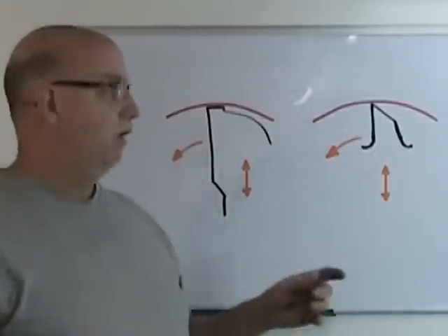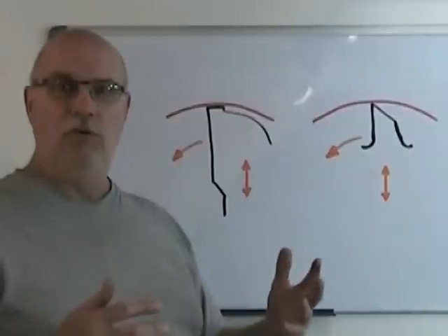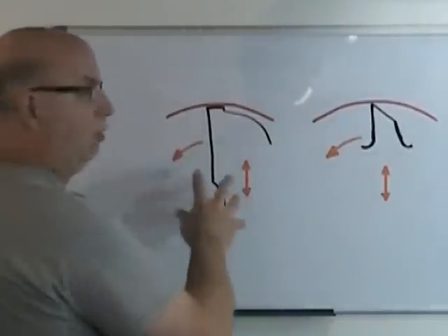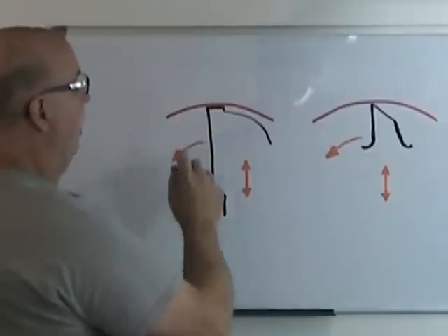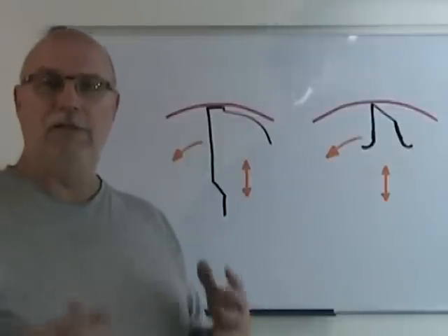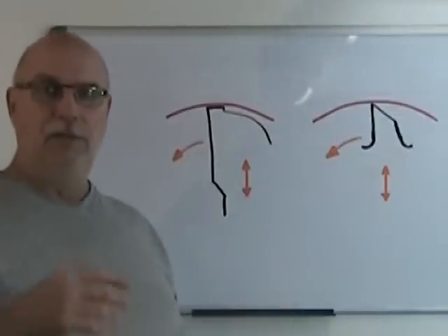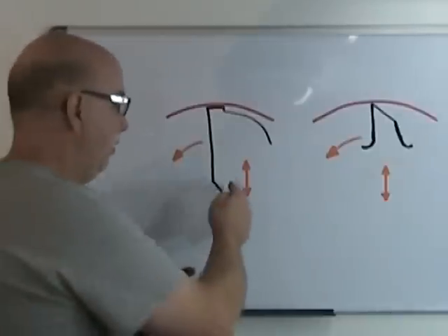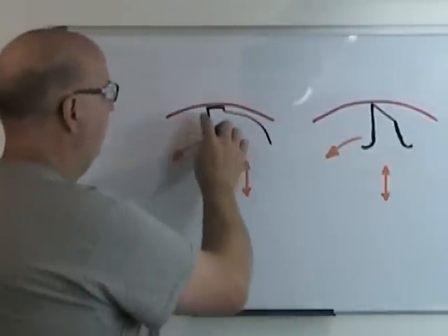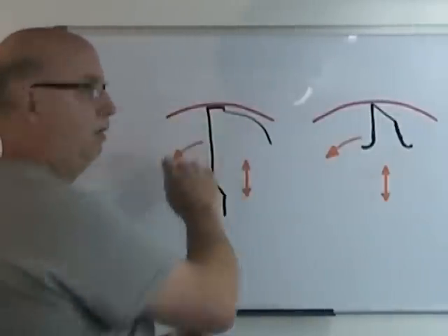It's not made to produce completely a hole, and there is no chisel edge or center cutting action on a reamer, because you can't have those equal on both sides and still get something that's accurate, because this tool, the drill bit, is center cutting. If it had a cutting lip on its edge there, well, something would have to give, because you can't have one thing and its opposite at the same time. There has to be a boss, there has to be a leader, and in this case, the leader for keeping the drill bit on track is the chisel edge, coupled with the angle of these chip producing cutting edges here. But that has nothing to do with the margins.